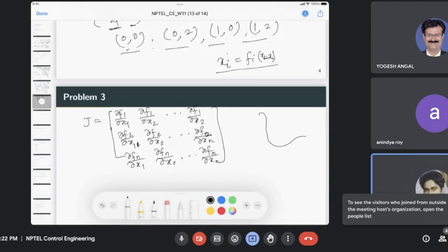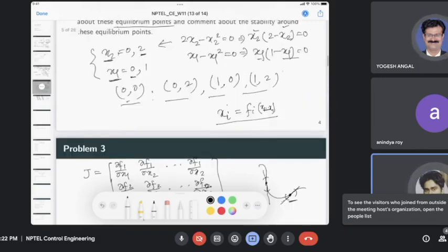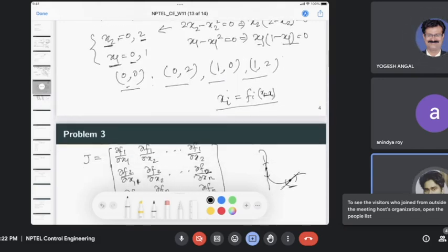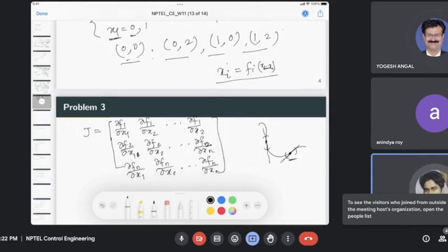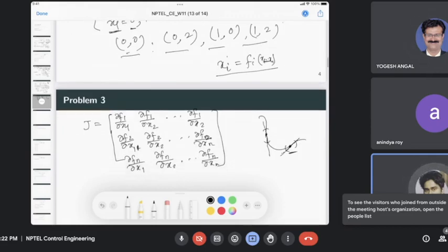But if you think of a small neighborhood of one point, we can find a linear approximation there that closely matches the curve. Because this is a nonlinear system, we cannot say any result for it globally, so we pick points where we analyze the system and linearize around them. This is what linearization means.